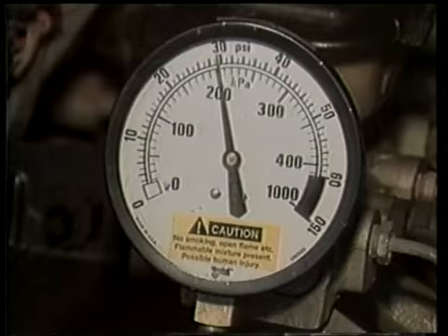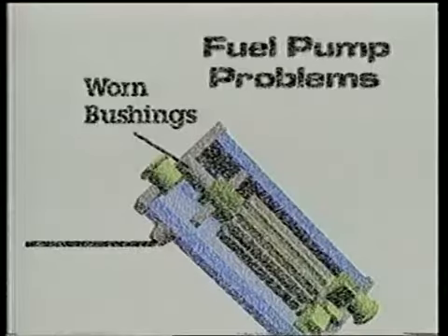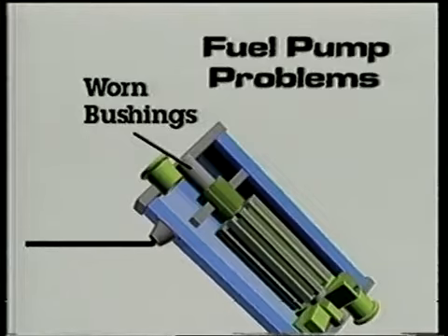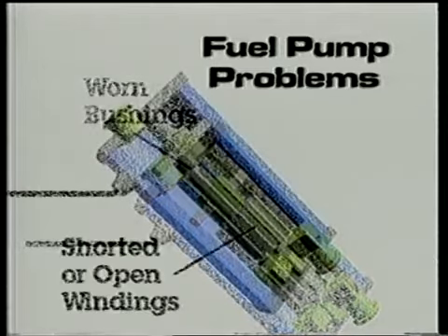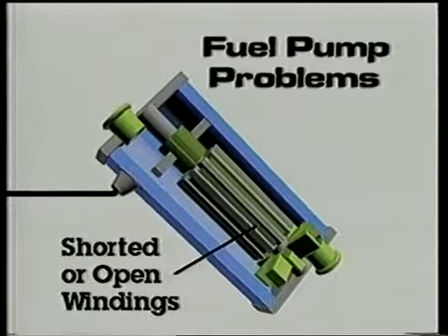Fuel pump problems are fairly common. Worn bushings in a pump will make the motor drag, increasing current draw and pump noise. Shorted windings in a fuel pump will often blow the pump fuse. Open windings will keep the pump from turning on.